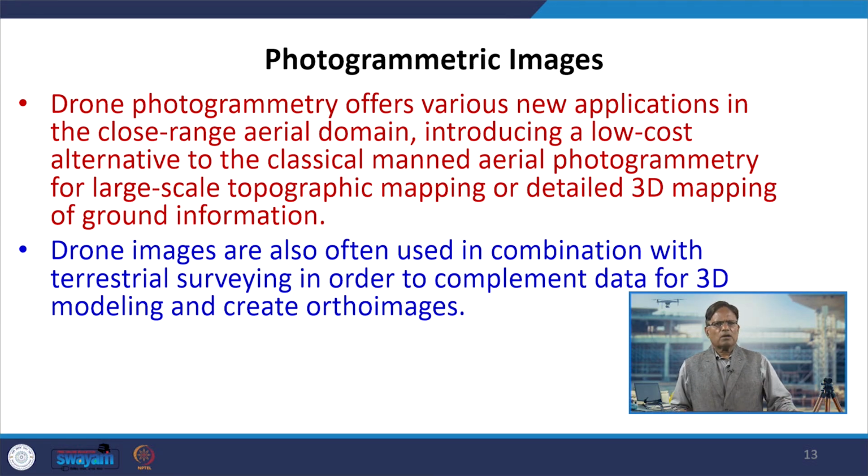Drone images are also used in combination with terrestrial surveying. So, that is called data fusion. We have data from terrestrial surveying and we can fuse this data, merge this data along with the drone images in order to complement the data for 3D modeling and creating ortho images.